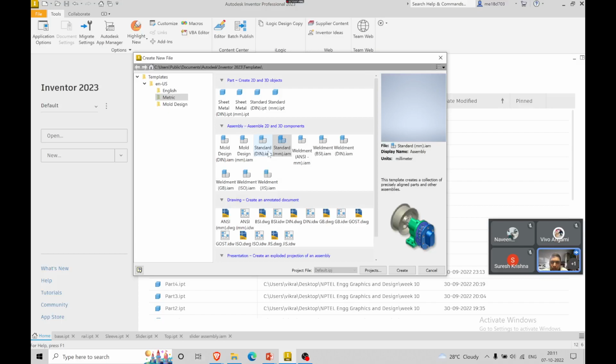So now we click the base. So select the document, slider assembly. So we see one base front view has already been generated. So let us increase the scale, probably 3:1. So you can see that the front view is there. So if you see the slider, this is a slider, so exactly as this will be our front view, this will be the left side view.